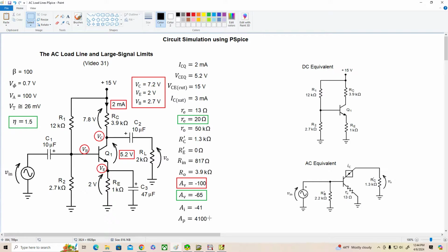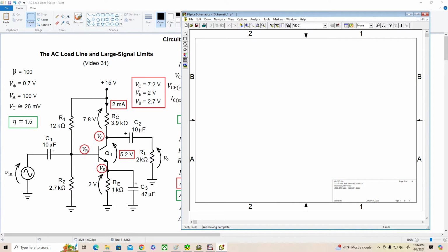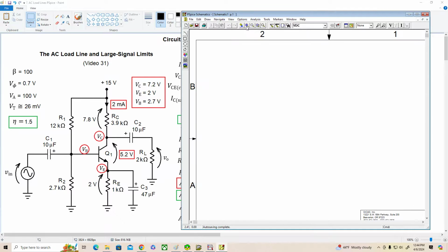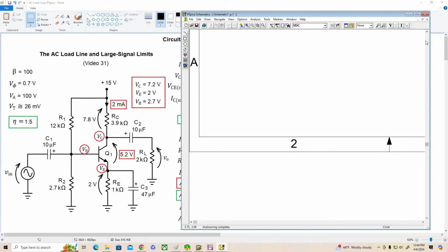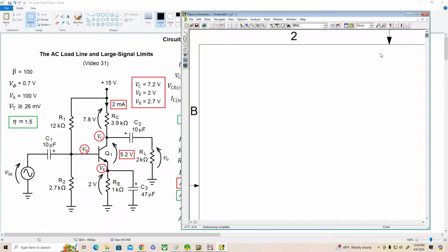So with that in mind, let's just call up the PSpice schematic editor here, and you'll notice it's a pretty big page, and I'm going to zoom in a bit to make my schematic a little bit larger on the screen. So if I come in 3 levels or so, and I like to start in the upper left hand corner of the screen as well, and start drawing. Here's what we've got: a blank sheet of paper. Normally this page would have a lot of grid marks on it and so on, but I like a clean schematic, so I've turned off things like fancy colors and stuff like that. So we'll get a nice clean schematic, and we're going to start by placing our transistors.